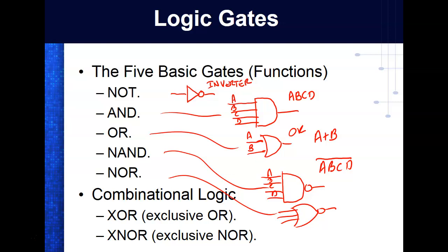Truth tables are nice, but we have an LS 7430, which is an 8 input NAND gate. With 8 inputs, the truth table for that gate would take 256 entries. But it says all highs gives me a low. Once you learn those little terms, you don't need a truth table, right? So here I would say all highs gives me a low out. Here I would say all highs gets a high.